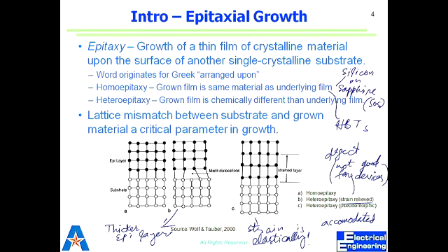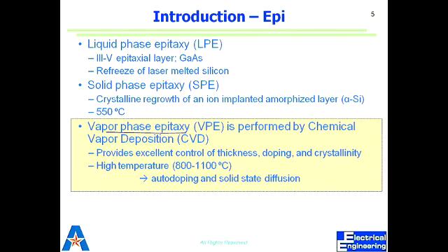Or you can make the material graded in concentration. It's not concentration, that's what you call that. Sort of an alloy. So in silicon germanium, you can make 0.7 of silicon and 0.3 of germanium, and you can go further away and completely change into germanium. So you have what you call a graded junction. In a graded junction, there's no immediate change in the lattice constant. It gradually changes. So that's to reduce the dislocations, the traps.